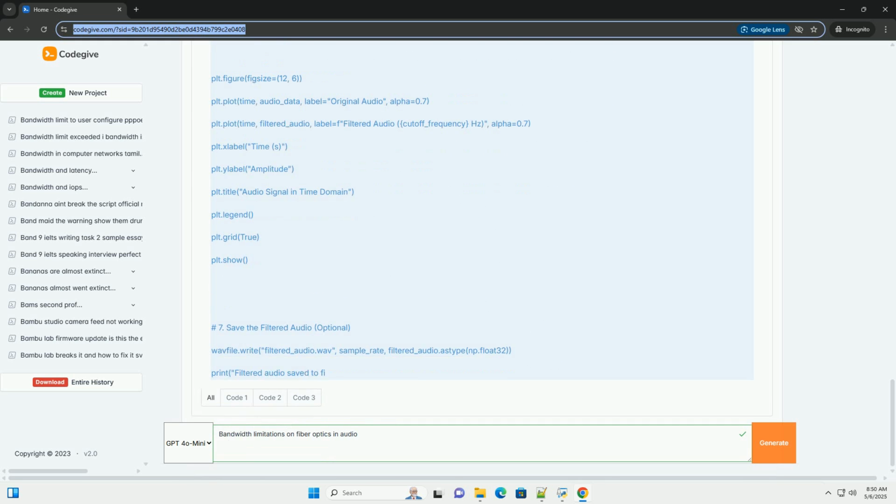3.3. Attenuation. Attenuation is the loss of signal strength, optical power, as light travels through the fiber. Attenuation is caused by absorption, scattering, and bending losses within the fiber. Excessive attenuation reduces the signal-to-noise ratio, SNR, at the receiver, which can limit the maximum data rate and audio quality. Attenuation is typically measured in decibels per kilometer, dB/km. Lower attenuation values are better.